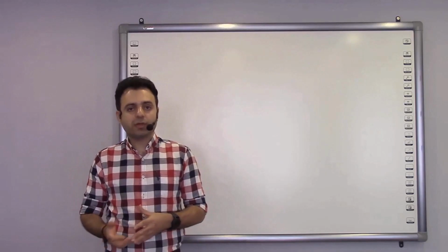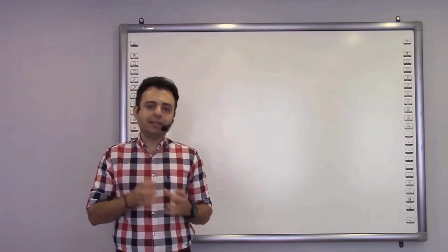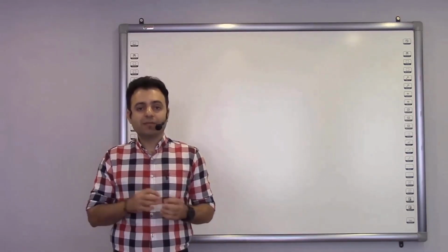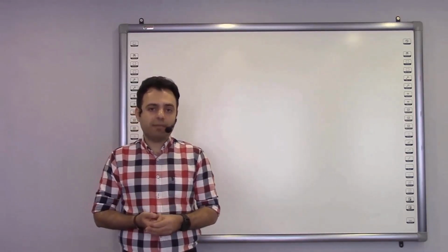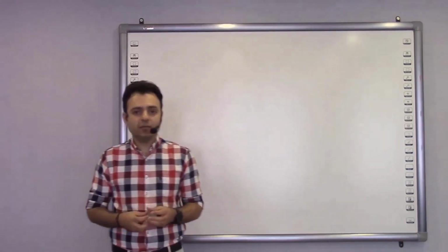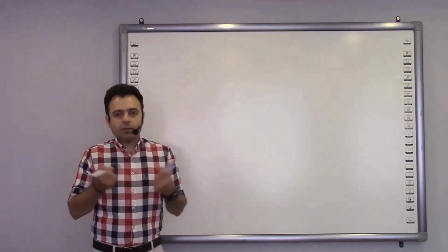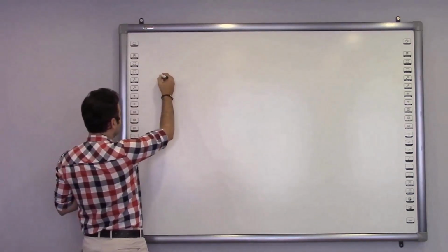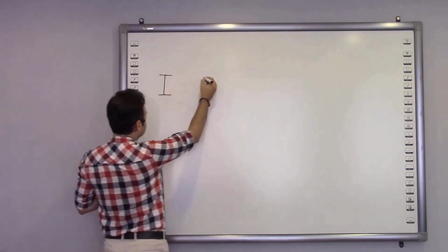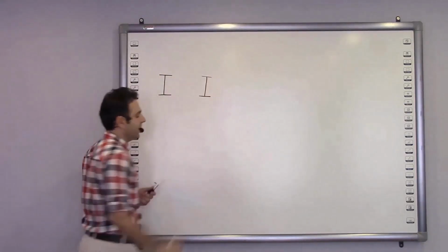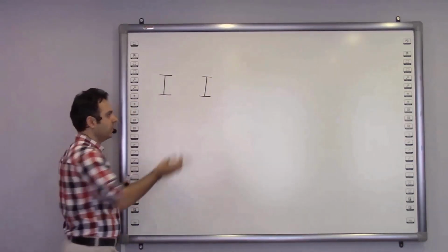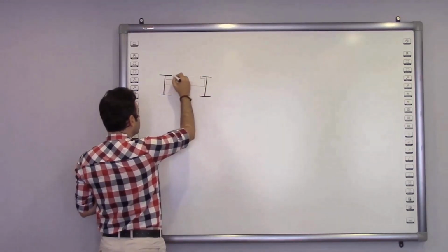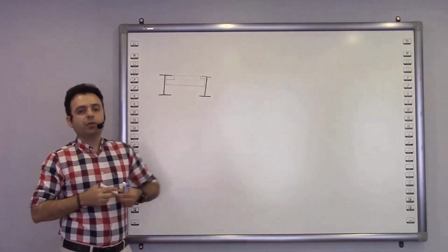Before we go to Revit and start drawing there, I draw you a detail from the ceiling so that we can get familiar with the technical objects and then we will start drawing in the software. So let's analyze the details of a ceiling. If I want to draw you a simple detail of a ceiling, first of all I need to draw the main beams. So imagine these are the main beams, right? And then the secondary beams. See, that's the secondary beam.